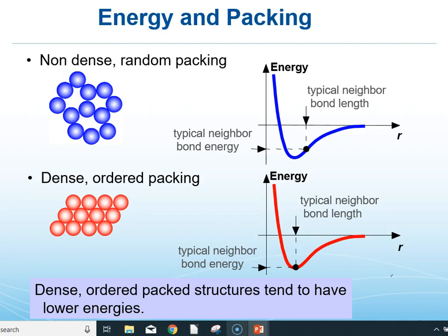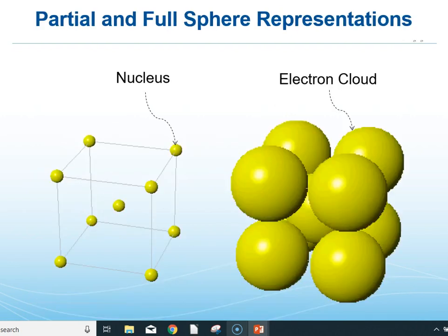And in fact, the average spacing between atoms in a crystal, a characteristic of that periodic array, is going to truly be that interatomic spacing, that R0, which we can calculate if we have the A's and the M's, the coefficients and exponents for our attractive and repulsive forces. So condensed materials, solids, will crystallize because it minimizes overall bond energy in the structure.